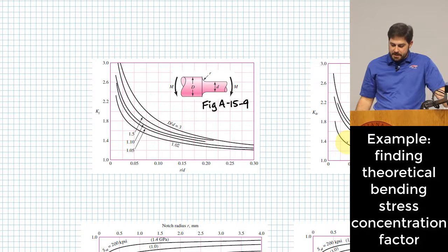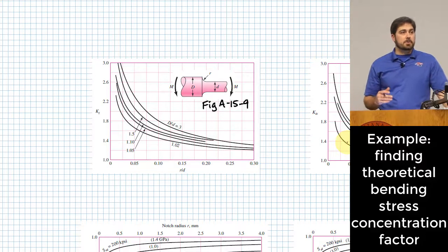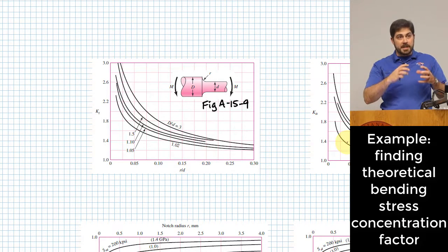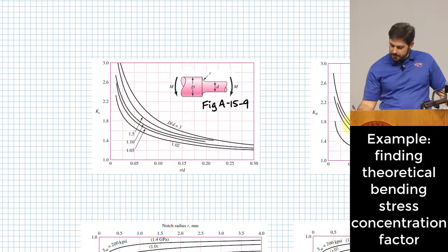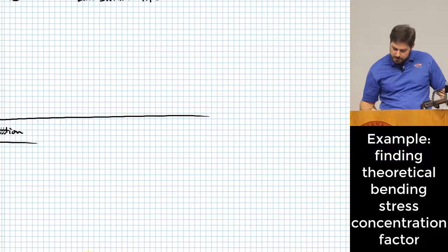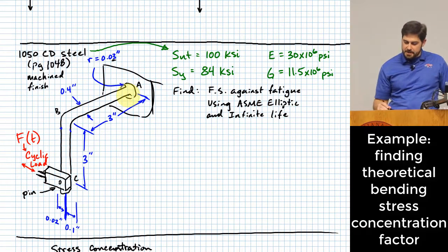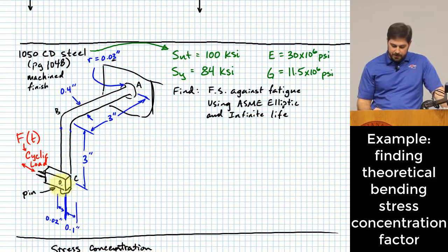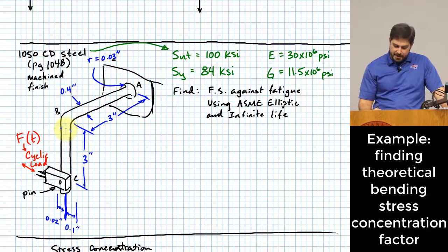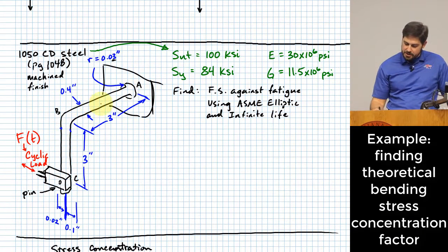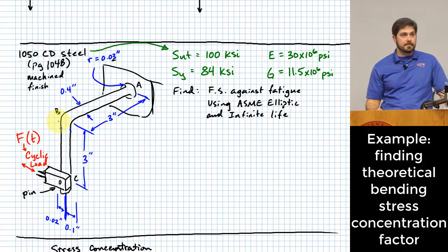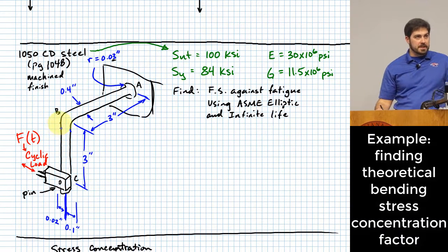So this is for the flexural part of this, and probably a comment I should make there is that this rod experiences both twisting and flexure at the point of support. Okay, you imagine this, it's experiencing twisting due to the fact that this rod is attached to this lever, and that creates a twisting action around AB. Right? But what else does it experience?